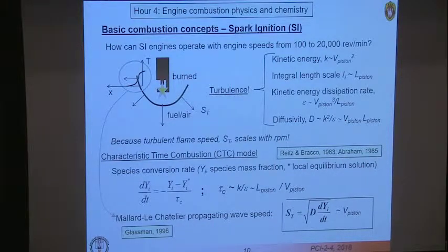Now, at first sight, you say, well, we're all done, right? So spark ignition engines, we can close the chapter. But nowhere here did I say what kind of fuel we were running. And we know that with different fuel, we have different flame speeds. So somehow this model doesn't capture all of the information. And in fact, to this day, we still don't really understand how fuels influence the turbulent flame speed. And I'll talk more about that, obviously, as we move along here.